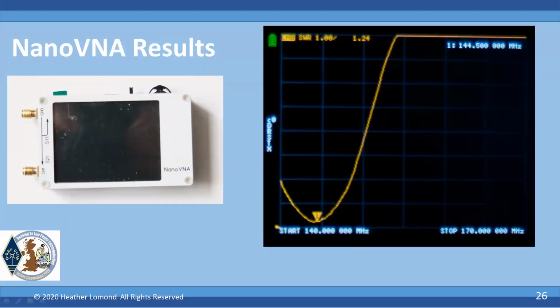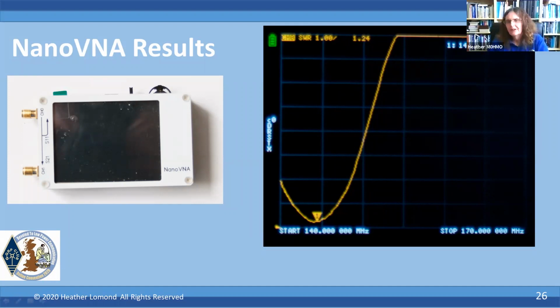Reduce. How do you reduce the SWR if it's already on the correct frequency? Well, I'm not sure you can. There's always that difference between resonance and... Need to add some tuning element. Yeah, Paul's just shouting over, if it's already at the right frequency, the main things that affect the SWR of an antenna are the shape of the feed point.